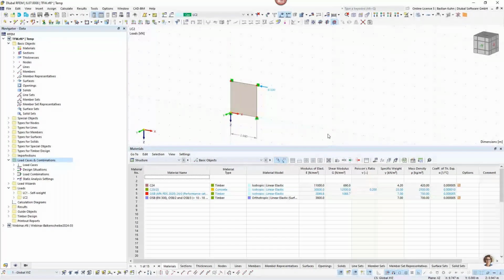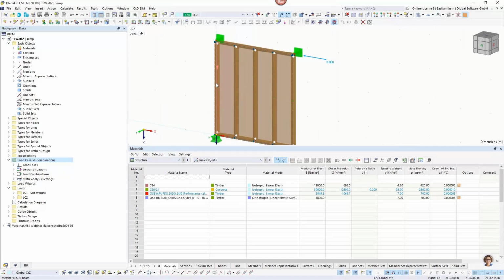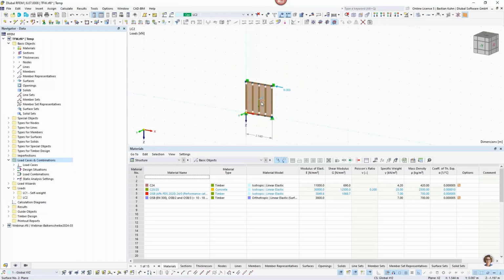Why is nothing changing so far? The answer is because I have not shown the beam panel. What our idea is from developing the beam panel is that you work with, as you know it, with surfaces. And then inside it, you generate the beam panel. And when you now activate the beam panel, you can see that it's generated in here. So here is the top beam and the bottom beam, and also the posts. So we have 5 posts in here. But obvious because of our distance.